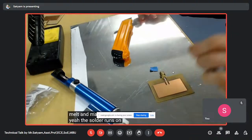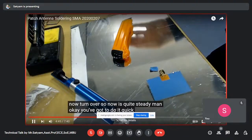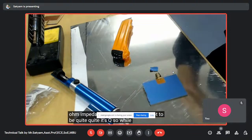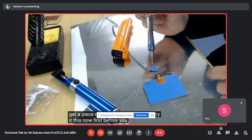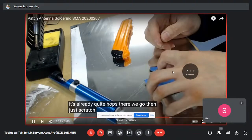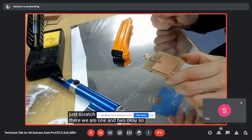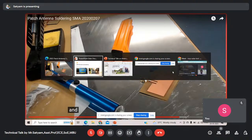You can see some liquid, and that is usually what they do. You've got to do it quite carefully, so you've got to be quite choosy. What I would say is get a piece of waste PCB and just try this out first before you do it for real. Some solder. Oops, solder off. There we are. One, two. Okay. So now the next thing is that I use something called a piercing tool.